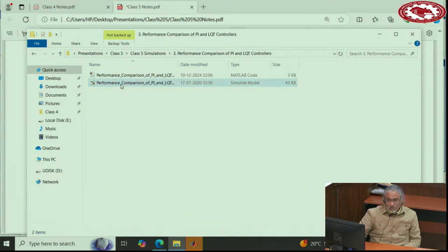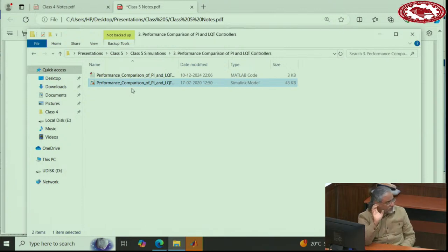Yeah, you need to select that low pass filter properly. Again, the design of that low pass filter. Remember, why do we put that low pass filter? To help the current limiting, right? And remember, this is outside the loop, not inside the feedback loop. If it were inside the feedback loop, yes. Now, this is outside the feedback loop. If you put too much delay in that low pass filter, it does not help a lot, because when the grid voltage drops, you want it to quickly come to the control system.